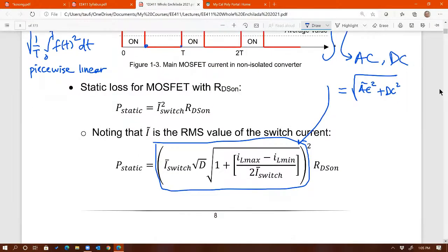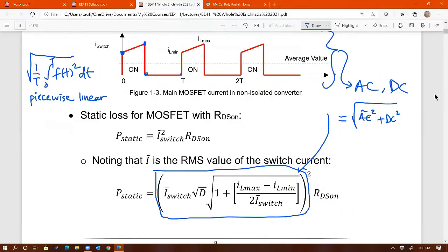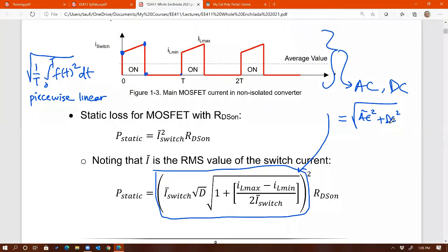I forgot how to find the AC component though. Don't you normalize it or shift it down so it has no DC component? That's correct, yes. To find the AC component, you take away the DC component of this waveform. What is the DC component? Another name for DC component is average value. The average value is this flat line right there. If you take away the flat line, then this whole thing will shift down to something like this.